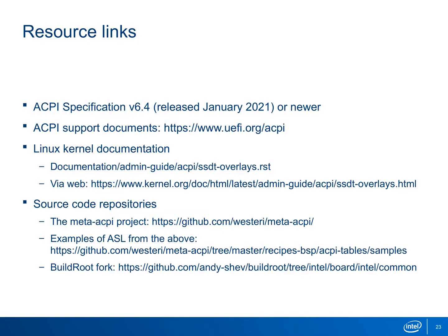To continue with the topic, the following resources will be useful. First of all, it's the ACPI specification version 6.4 as of today, along with supporting documents on the site uefi.org. In-kernel documentation specifically related to SSDT overlays. Additionally, it would be good to look into a couple of repositories. One of them is the Meta ACPI project, and another is our fork of buildroot, which brings a few scripts to make everything easier when you create an image based on buildroot.